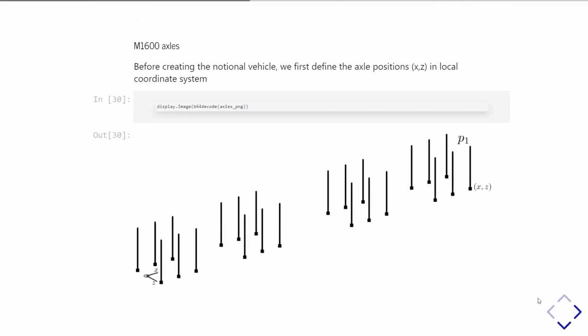For the truck axle itself, we would then use the idea of compound loads. We'll compound multiple points together to form this truck model here, and that's for 1 lane. So we do that for 3 lanes as well. We can do that using compound loads.